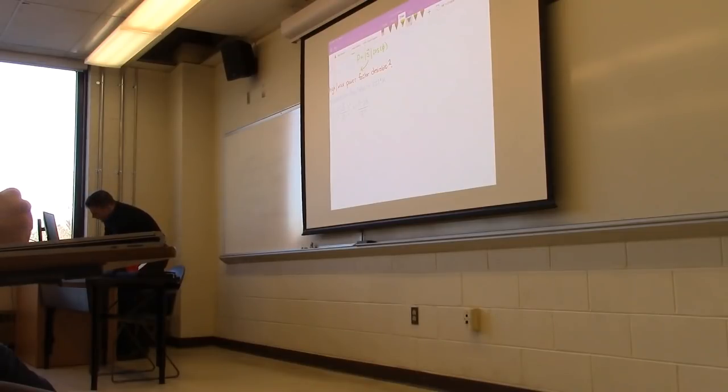And then if we split that up into the magnitude and the phase, we end up with the magnitude of I being equal to the square root of P squared plus Q squared divided by the magnitude of V. Because you take the square and then the square root of the same thing, we already have that value.